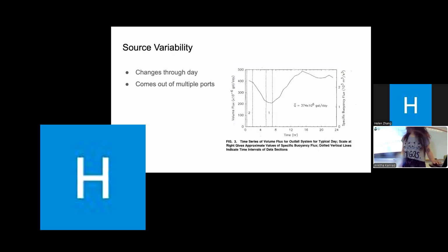Okay, cool. This is that daily cycle that I was talking about. People don't poop as much at night, I guess. And we produce a lot of wastewater in the morning, kind of a dip, and then again in the evening. So it's really like a human behavior kind of thing. Hard to predict, but just keep that in mind as we look at all of our data.